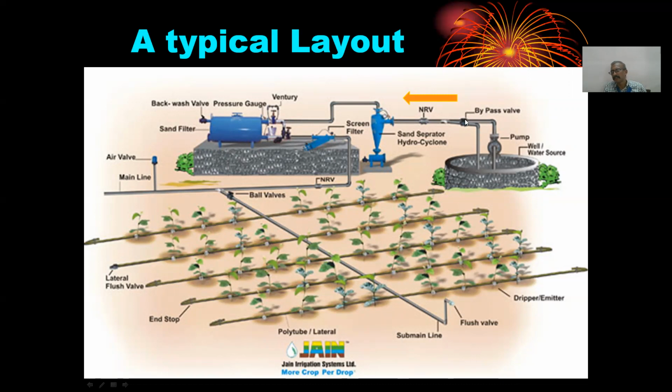And when you control like that, there is a possibility for centrifugal pumps. In case of most of the centrifugal pumps, the power used will also be less if, instead of using a bypass valve, you just use the control valve and reduce the discharge, and you reduce the pressure alone and allow the water to get into the system. That is a very good way, because the power consumed will also be less if you reduce the discharge.